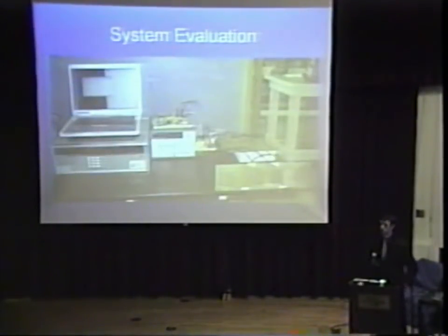To evaluate the system, I had to assemble the whole thing. And we actually did this in the back of the electrical engineering lab. This right here is my 4-element array. I have, kind of on the edge of a desk, a protractor in front of it so I can see what angle we're at. Using a test antenna that was set in the far field, which is about 50 inches away, and using a thin cable, we attached the test antenna so we could keep it at constant radius and then moved it from all the way off this side, all the way around 180 degrees to the other side, and took power measurements for the received antenna. That way we can find maximum power, which is where the beam's pointing, basically.